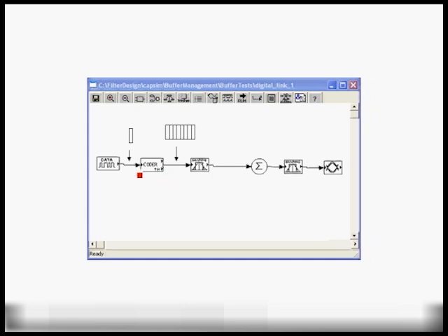So for every input sample, it'll generate 8 output samples. In this case, an impulse for the symbol and 7 zeros. These are input to the pulse shaping filter here, a square root Nyquist pulse shaping filter for the transmit side that will filter the samples. It goes to the add block. In this case, it is only passing the data through since we're not connecting any noise source yet.